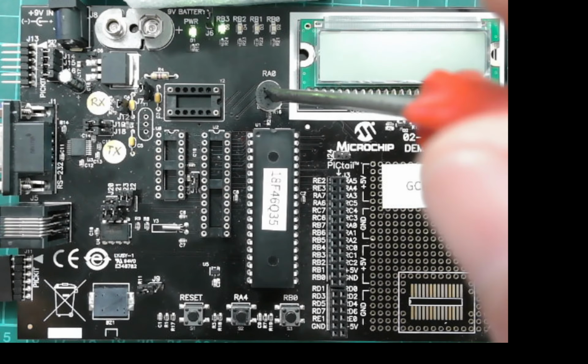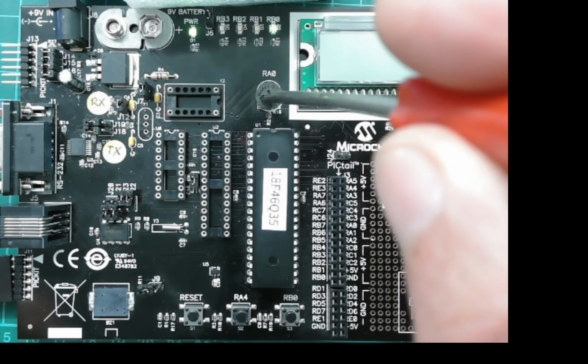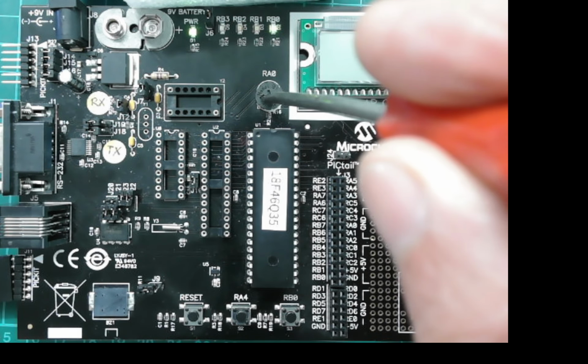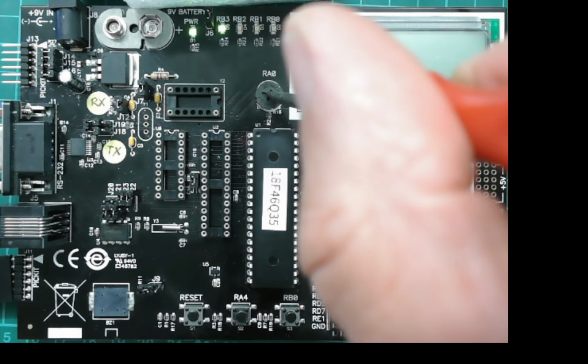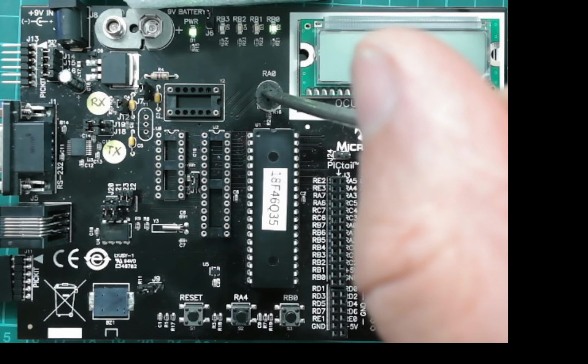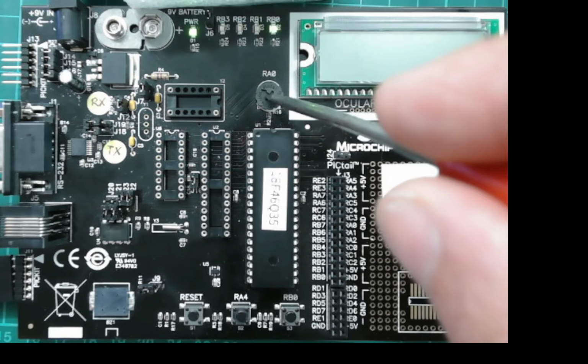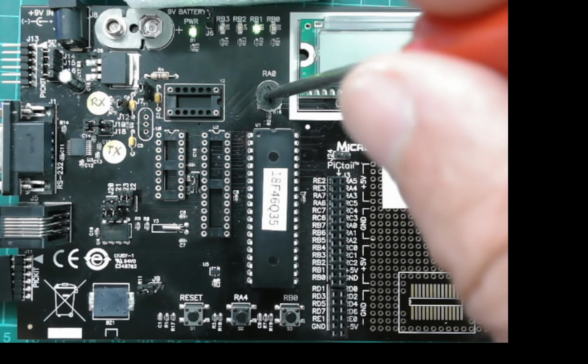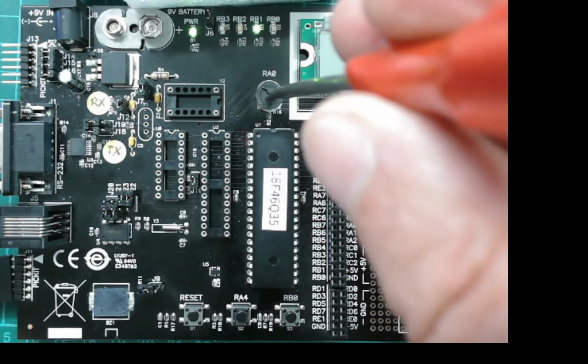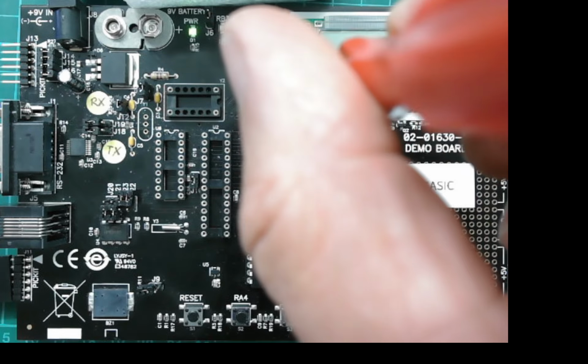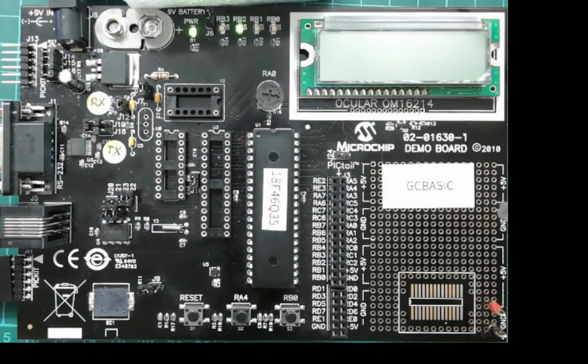Because if I rotate this, the reason I chose 50 milliseconds is hopefully you can still see those LEDs rotating. If I rotate it, it will go to 1 second per LED rotation. And back. So that tells us, by the way, that we know that that ADC is returning its correct values because that scaling is correct. Look, 1 second, 1 second. If it wasn't coming back at the correct value, it wouldn't be 1 second, but it is. Later on, we could put the ADC values on that LCD, and we can see the ADC values. We may do that later on.